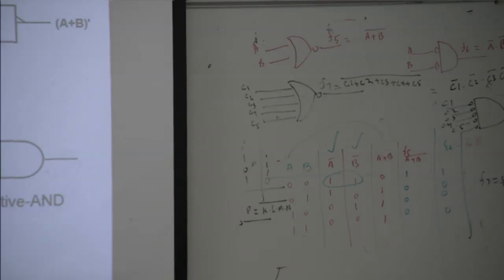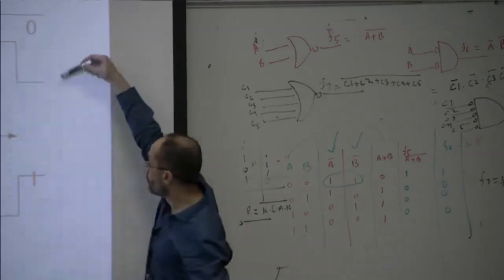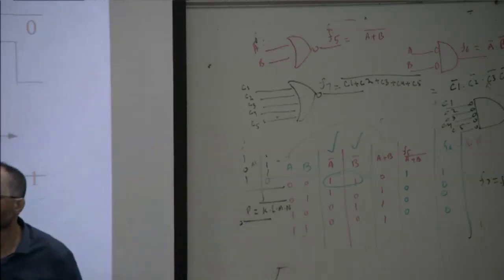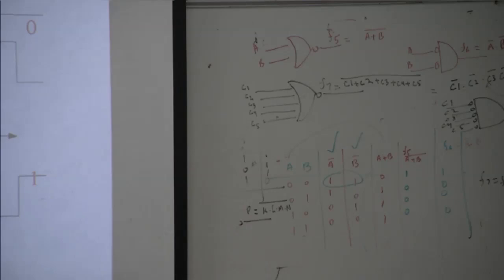Got it? So this is how it works for the different logical gates. Now, we say (A + B) whole bar is equal to A bar dot B bar. This is the timing diagram of a 2 input NOR gate. If all inputs are 0, the output is 1. If any input is 1, the output is 0. This is the logical description of any n input NOR gate.